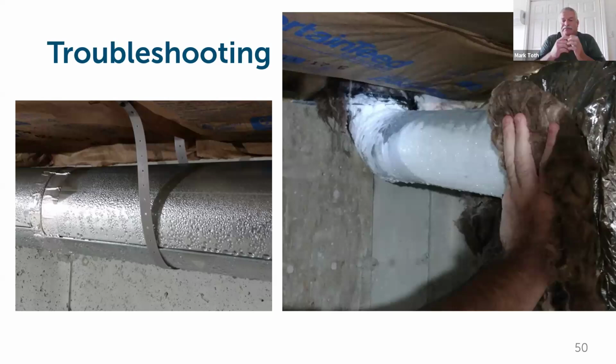Just what happens. What happens in the winter on the incoming line is that we are getting that happening, but it's freezing. So it's turning that into a popsicle. That's why these ducts on the incoming line especially have to be very well insulated and sealed. You can see by this guy's hand, actually it's my hand there, I'm pulling the insulation back, exposing that frozen pipe. The pipe is insulated. Yes, it was insulated, but it was not sealed on the two ends.